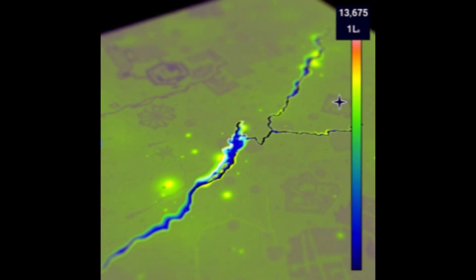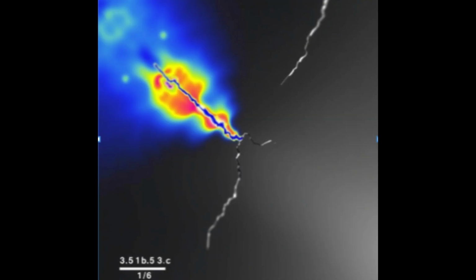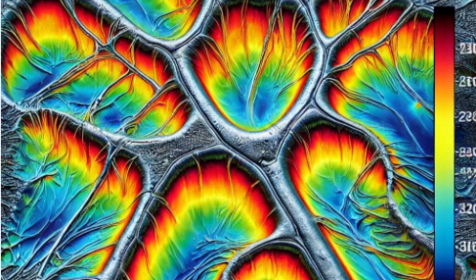Hydrogen-induced cracking presents itself differently. This internal corrosion can create faint, cold lines or cooler zones along the crack path due to the disruption of material integrity, which affects the heat flow. Stress corrosion cracking and cracking are both types that can form hot spots in thermal imaging. These hot spots indicate areas of high stress concentration, where the material is weakened and prone to crack propagation under thermal stress. Embrittlement, a condition where the metal becomes brittle, can also appear as hot or cold spots, depending on where the embrittled material alters heat distribution, often showing inconsistent temperatures along the affected region.